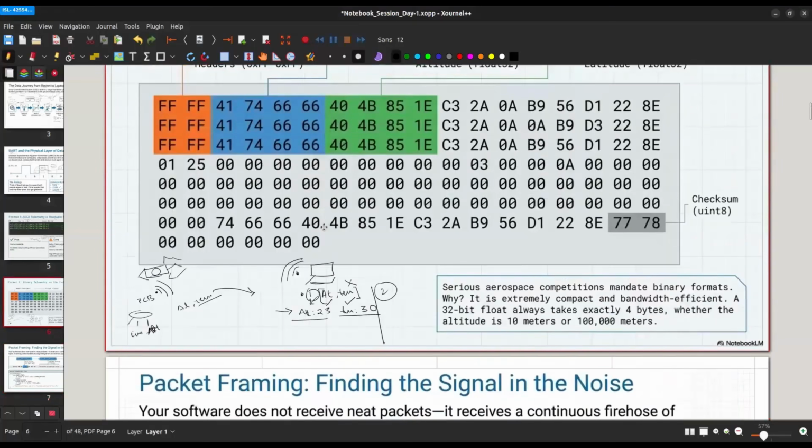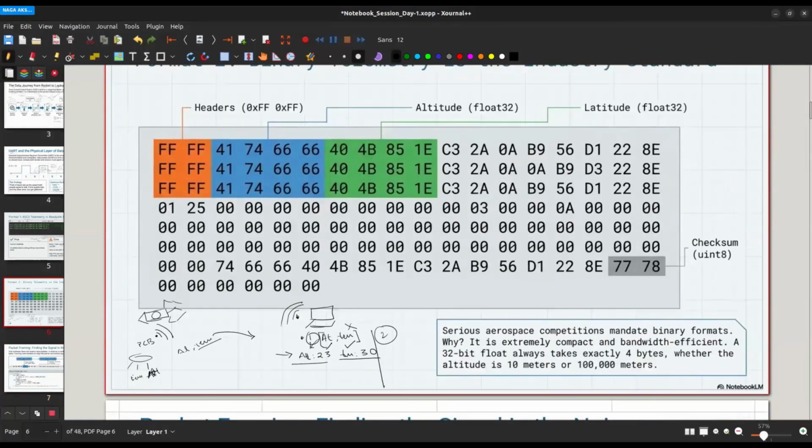Your GCS is hard coded in a way that it's only trying to receive values in the form of altitude and temperature. So let's say in a certain packet, there was some kind of transmission failure, and due to that the altitude value was not received. So it did not send altitude, it just sent some garbage values or maybe nothing. And it also sent temperature as 23. So the temperature was received fine. The GCS properly decoded the value.